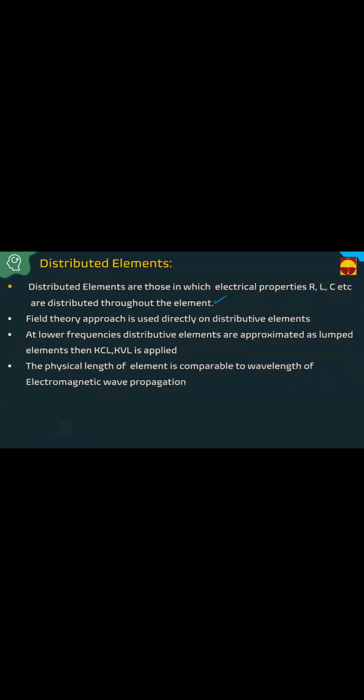The field theory approach is used directly for distributed elements. This is important, I told you already. For lumped elements only, we are using KCL and KVL. For distributed, we are using the field theory approach. At lower frequencies, distributed elements are approximated as a lumped element. Then only you can apply KCL and KVL.